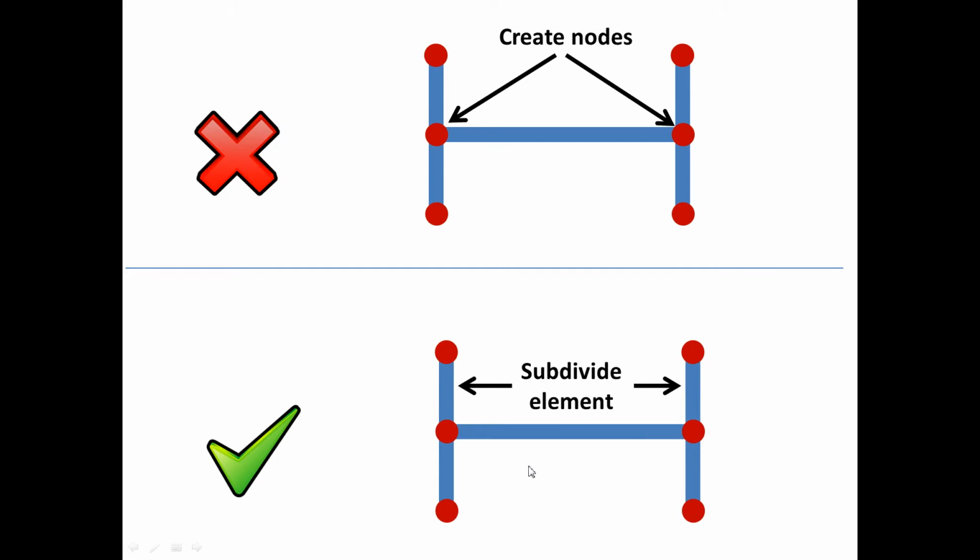And in this way, this node is connected to this column or part of this column, and connecting this new element is actually connecting to the column. And this is one of the common mistakes when modeling, but this is not really a critical one because you can check this if it's really connected using the dynamic analysis.